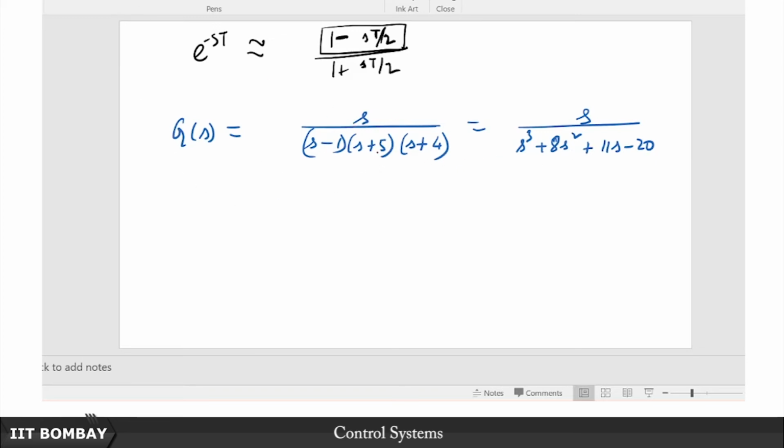So this is the transfer function. We have already seen, if you go back a few lectures, that for a transfer function such as this, the root locus sketch tells us that neither a proportional controller nor a proportional derivative action can ever stabilize this plant. So what option are we left with after all? Here is what we are going to do: we are going to use state feedback with an observer.